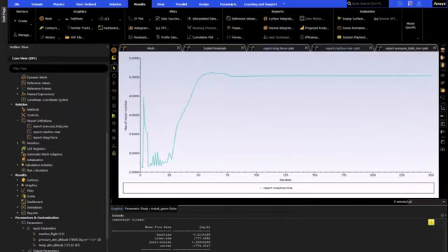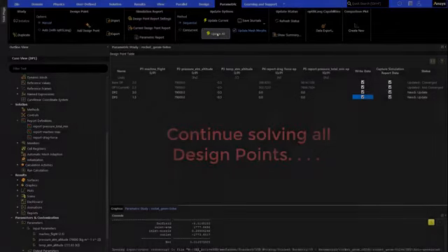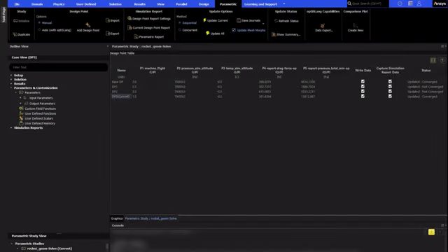To complete the parametric study, we'll continue adding design points representing a flight speed envelope from Mach 1.5 to Mach 3. By selecting Update All, Fluent will run all the design points where the status is Needs Updating. Depending on the computing load, you can run the required simulations either sequentially or concurrently. Once complete, the output parameters can be compared in the design point table.